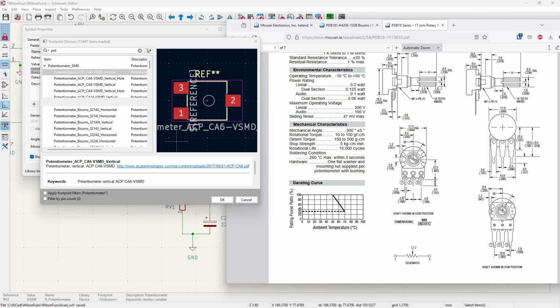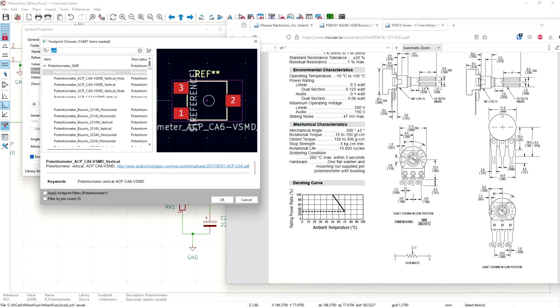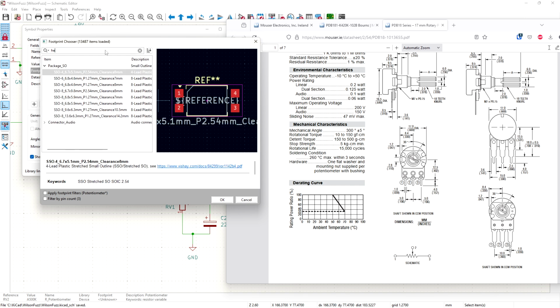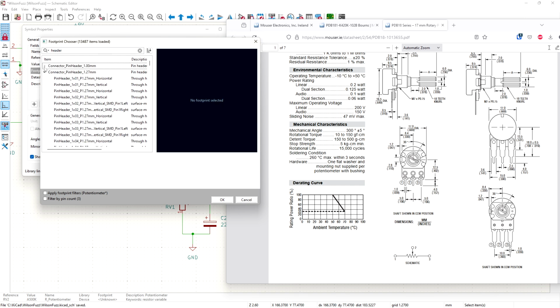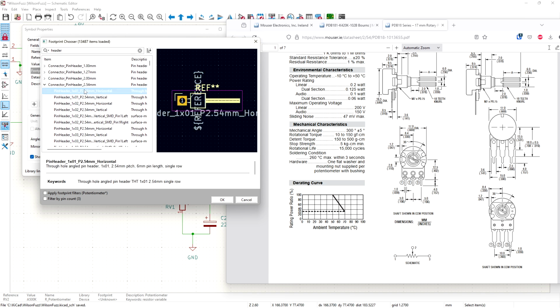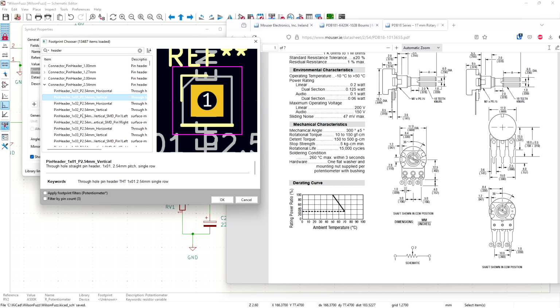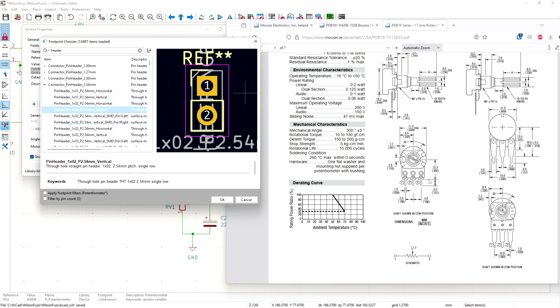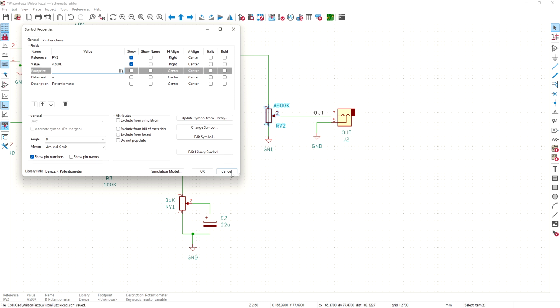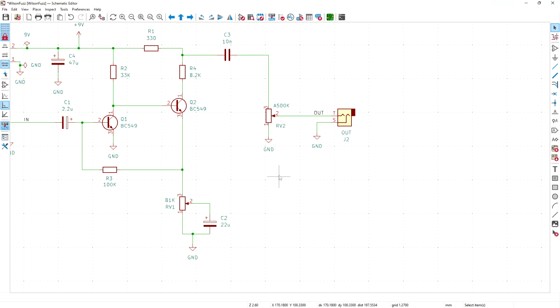And we ran into our first problem, because I couldn't find a footprint for this one in particular. Normally, if I want to do wire soldering, I just use a header and find, say, 2.54. The problem here is this one is 5 millimeters, so it won't work. I don't want to go into this right now, but I suppose this happens more often than not with components that we use. So let me show you.